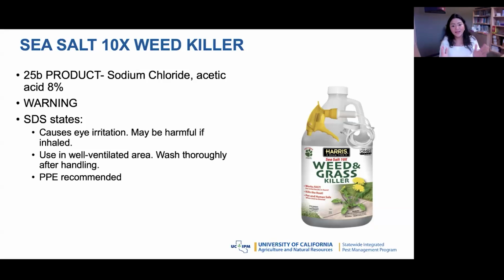That's something that maybe at the store you won't be told about, but if you go on the internet and look up the safety data sheet for this product, they will let you know that it should be used in a well-ventilated area, so never opening it in an enclosed space where you don't have enough ventilation. And obviously washing your hands thoroughly after handling.